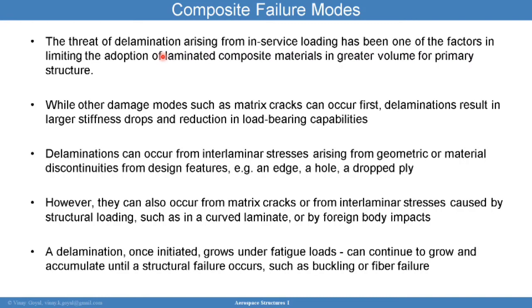And so why is that? Because the failure mechanisms for composites were not well predicted by analytical models. The analytical models were missing something, which is the reason why you test. I mean, you should test for a reason, and the testing was useful from that perspective. It exposed new failure modes that were not previously seen. But regardless, you can see how composites increase the layer. It adds a layer of complexity.